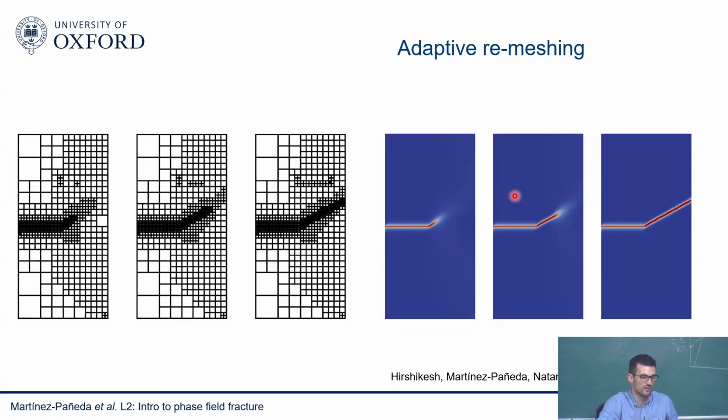That's what I'm saying. So normally, when I mesh, I just use a uniform mesh all over the place if I don't know where the crack is going to go. So what I would do, if I'm not using adaptive remeshing, is use maybe a mesh like this one, that I know is probably too coarse, but I'll put this mesh everywhere. Then I'll see that the crack is deflecting in that direction. So then I will use a finer mesh like this one over this square in the second calculation, and that will be the end of it. But you can also use these kinds of techniques where you start with a mesh like this, and then depending on the phase field, you start making your elements smaller, smaller, smaller, and then eventually you get the right result.